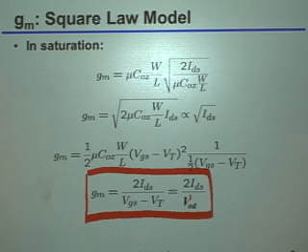The other thing which you mentioned a little bit about was swing. So maybe I'm going to bug somebody else about swing. How does this overdrive, or more particularly this VDSAT, influence the swing you can typically get out of an amplifier? And by swing, I mean the voltage swing. Yeah? For square law, I thought it was the minimum voltage that you have to have for a VDS to be in saturation. Yeah, exactly.